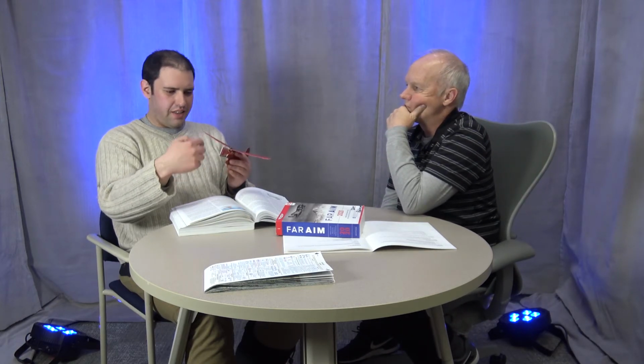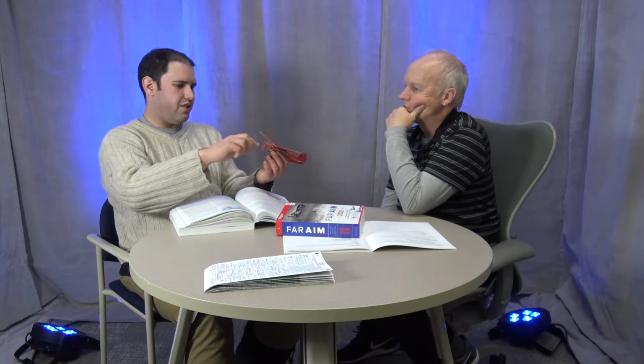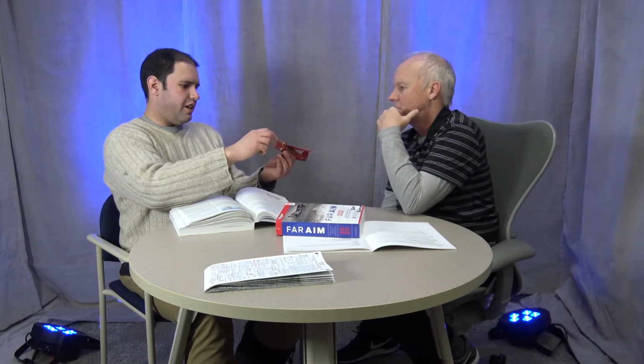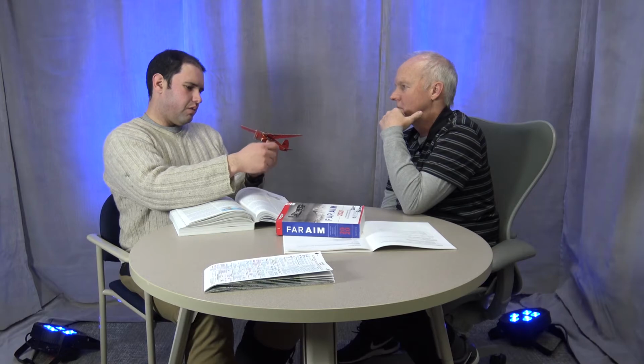As the twisting slipstream, I'm sorry, I had that backwards. So that would be for a left turning engine. For a right turning engine, the air is coming down on the right side of the airplane. It's hitting the left side of the rudder. It's turning the nose to the left.